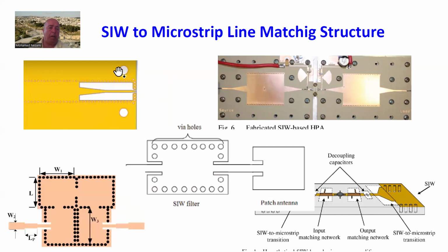And then a lot of times on a PC board, you might have a high frequency 2.9 millimeter connector, like in this case here, an edge connector, where you go from coplanar to microstrip, and then again you want to go to substrate integrated waveguide using this taper in here.